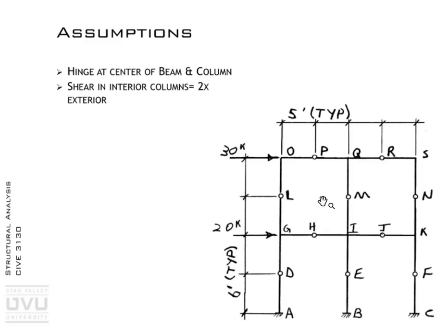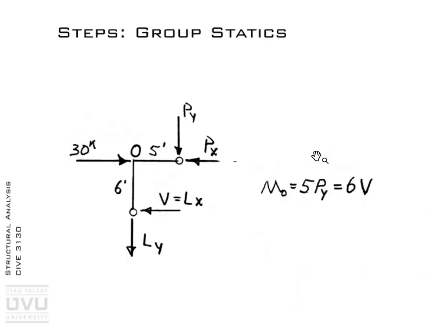And if I really wanted to make it quick, I could start up here and say, okay, if I take that as my free body diagram, I have 1, 2, 3, 4 unknowns. But if I sum moments about here, I can get this vertical in a relationship. Sum moments here, I can get that in a relationship.